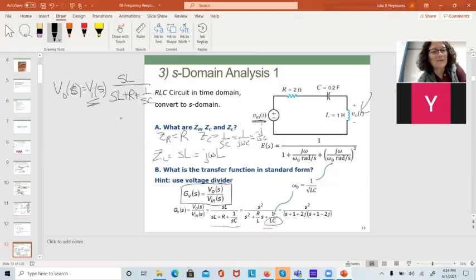If it's an RLC circuit, it's amazing how this works. How many arguments I've won by saying, well, what's the frequency? It's 1 over root LC. Oh yeah, of course. Whether it's a series or a parallel circuit, if you're dealing with RC circuits, your omega naught is 1 over RC.